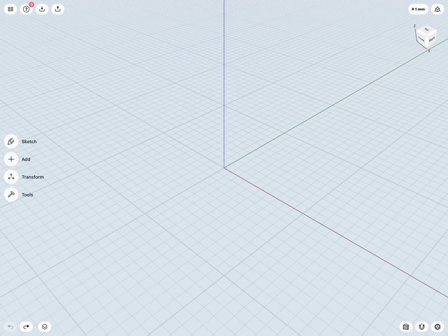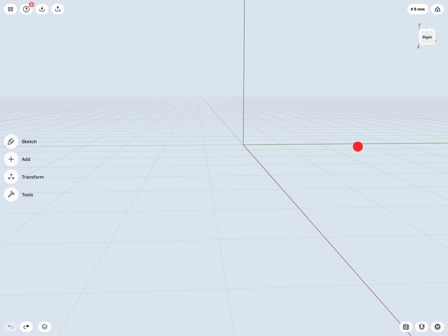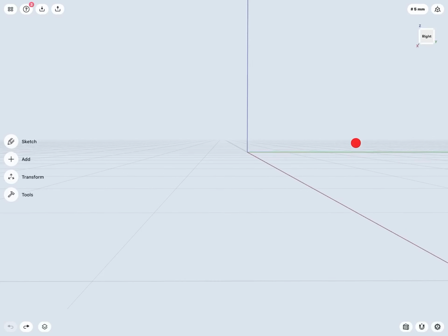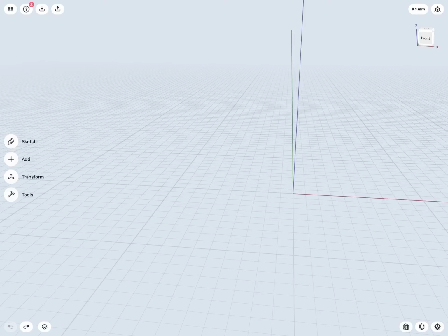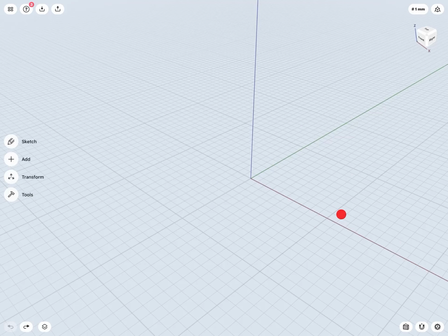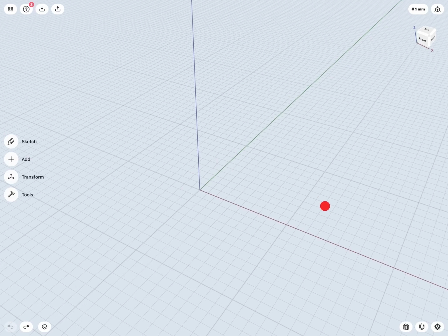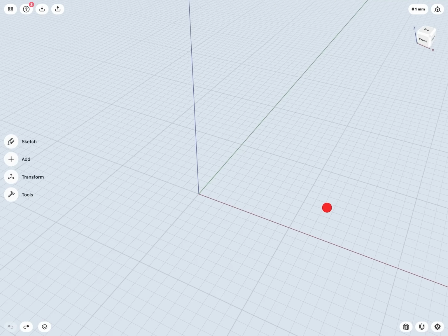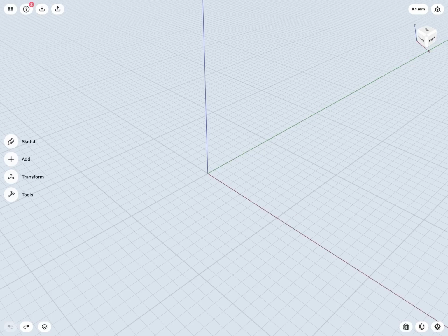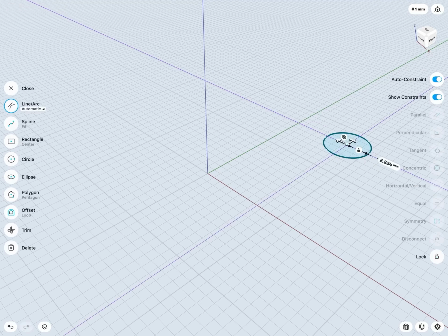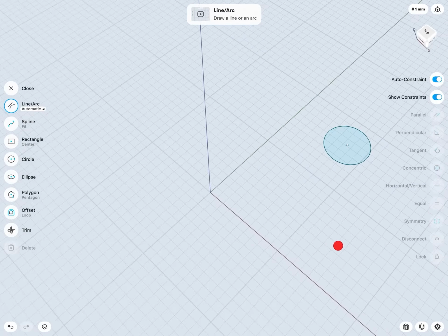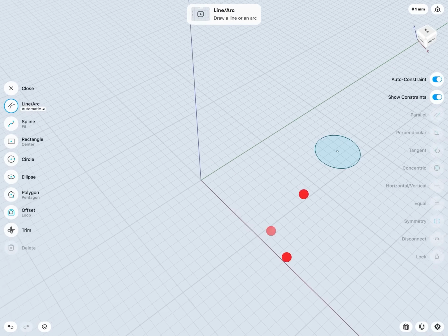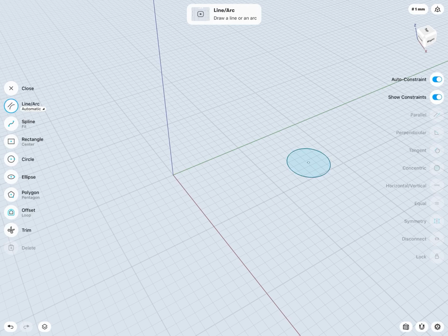Versus in my 3D view, I have my right plane would be the ZY plane, as we can see, and my front plane would be the XZ plane, for example. So again, by default, notice my grid is always on that top plane or that XY plane. And if I were to draw in a kind of 3D view here, notice it's always coming in on that top plane or that XY plane, as we can see here. But we do have a few options if we'd like to draw on some other planes.